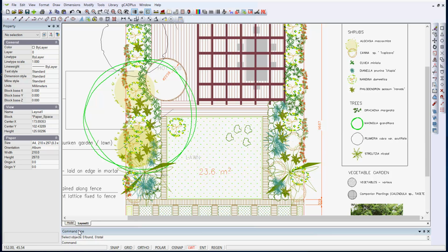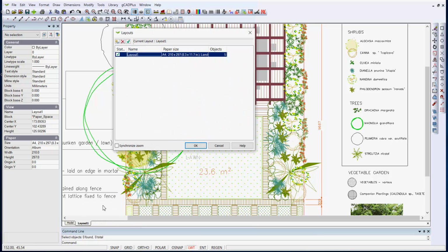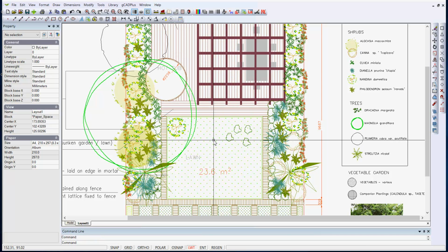I did mention that we would look at the size of that sheet, and that's done by Layouts Manager, and I can see this here, this layout is simply on an A4 sheet, which I'd be inclined to, for most drafting purposes, set as an A3 sheet. If you have an A3 printer attached to it, you can print to your own printer, but if you don't, you can always print PDF and then take the PDF file to your local copy centre and get it printed out on a reasonable size sheet to give your final design to the client.